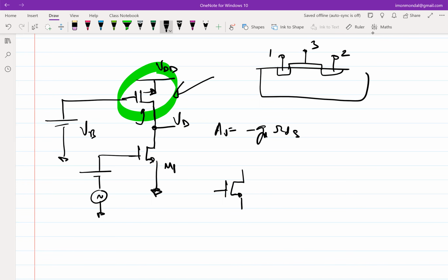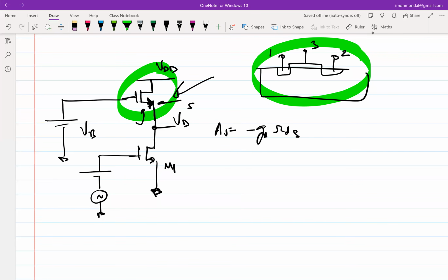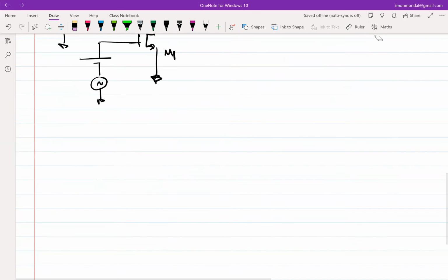So what I was trying to get at is that this is essentially a symmetric device. So how do you discern a source from a drain? Basically the one that is at higher potential is the drain, right? It's not as if you flip the device, the drain changes. So even though you have connected it like this, this will still be the source, which means the accurate way of representing it electrically will be this. So obviously I cannot use an NMOS, but fortunately we have a complementary device, which is a PMOS, where the current and the voltage directions are opposite.